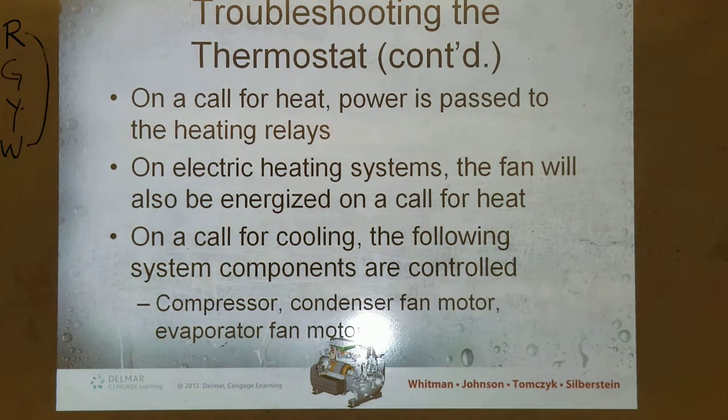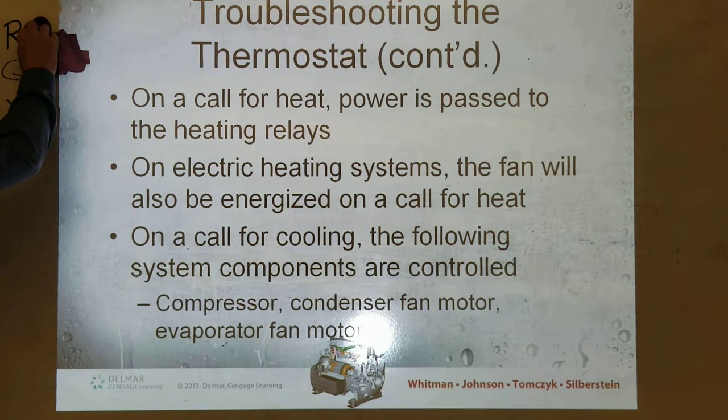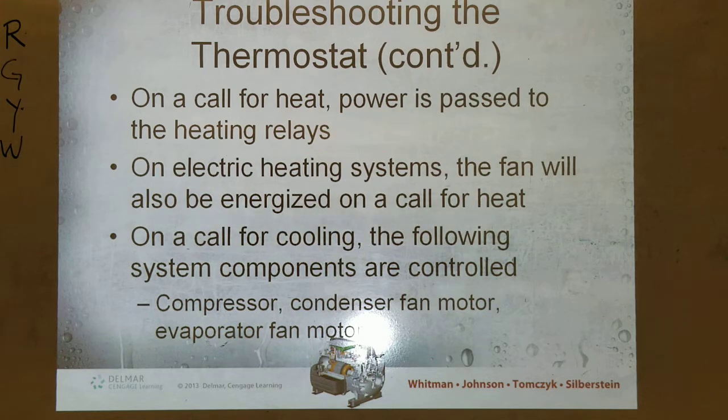Gas heat is not going to bring on the fan. Gas heat is just going to bring on the burner, the furnace. The fan will operate on another circuit. And then when we bring on just the fan, that's what happens inside the thermostat, those connections are made. You understand how the thermostat works now? Good.